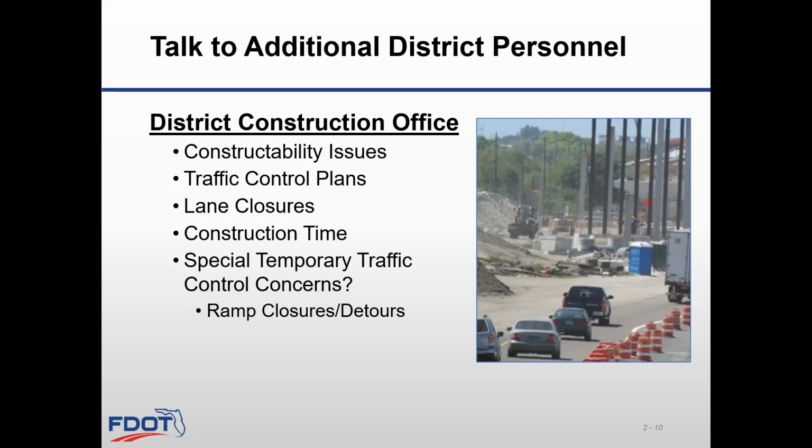Closing the 2 lanes allows enough space to cut the slab and set the equipment to lift the slab and bring the truck to pour a new slab. Coordinate any ramp closures, special detours if needed, and lane closures to get work done.